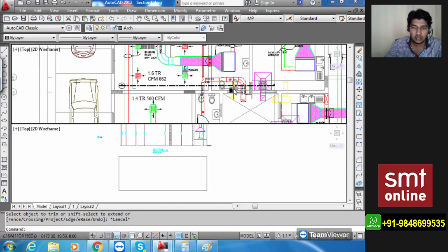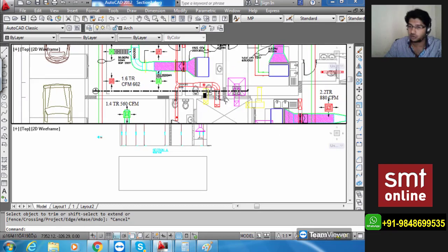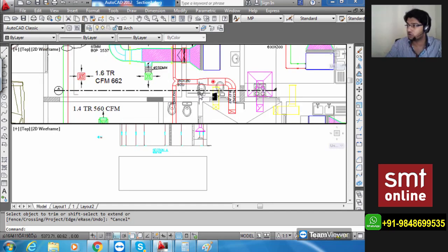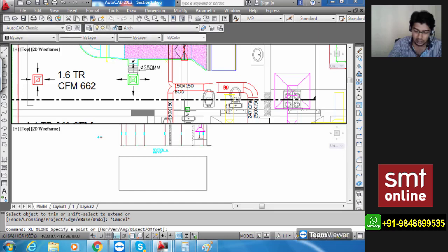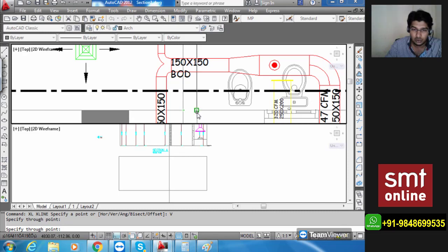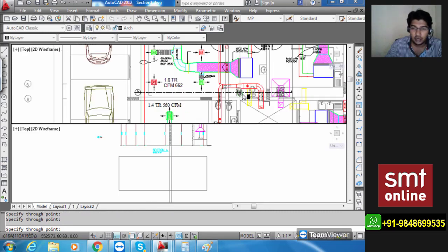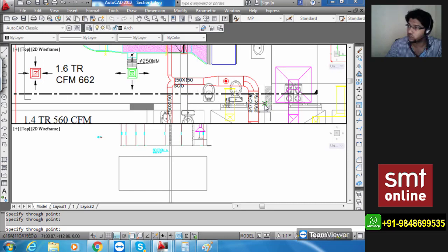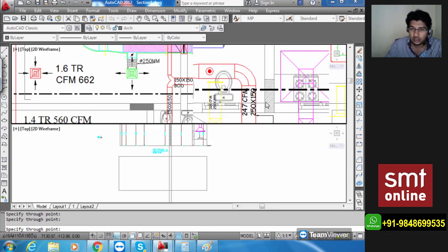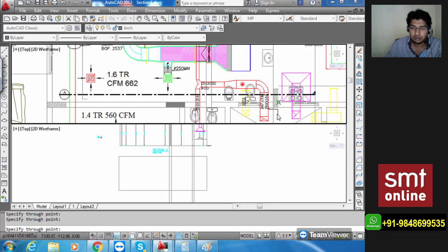Now from the main drawing again, I have to see for where are the walls, where are the columns and etc. for me to create the partitions for running the duct, the diffusers and etc. Fine. So from the starting, from this portion A, I am having the first wall here in this portion. So Excel enter, V enter once more, keeping your architectural layout active. I'm going to create on the first wall portion and you can see that is created below. From there, what is the next architectural part or the structural part is the column. This is one, this is second. So now from these two boundary areas, this becomes a concrete structure, this becomes the brick wall.